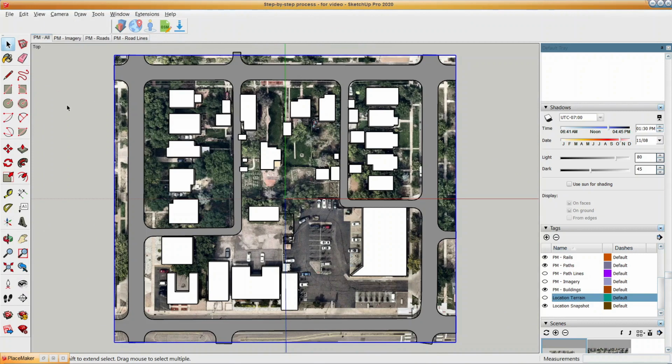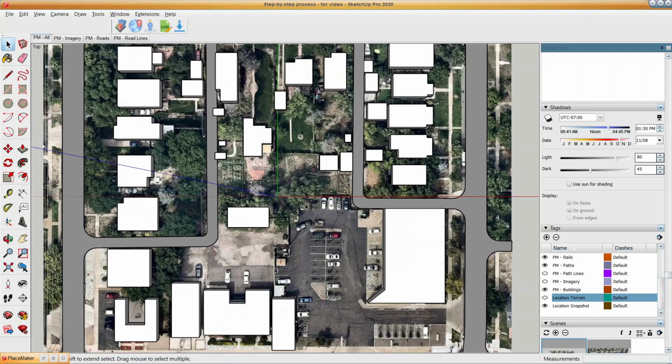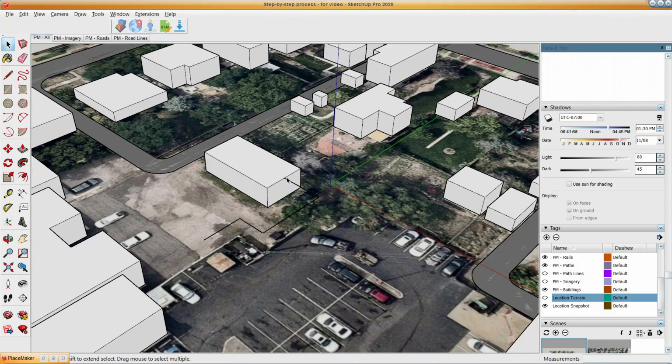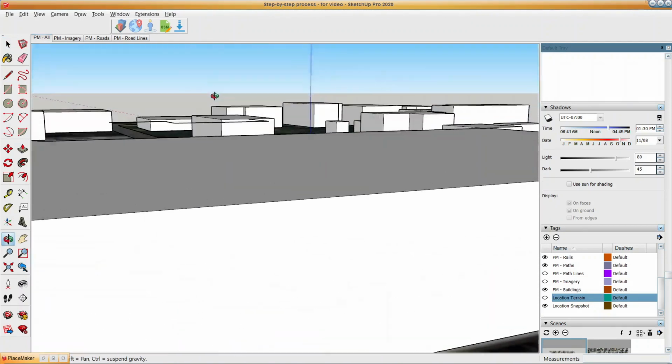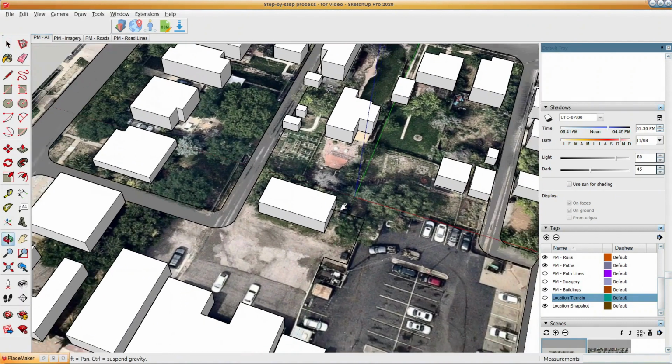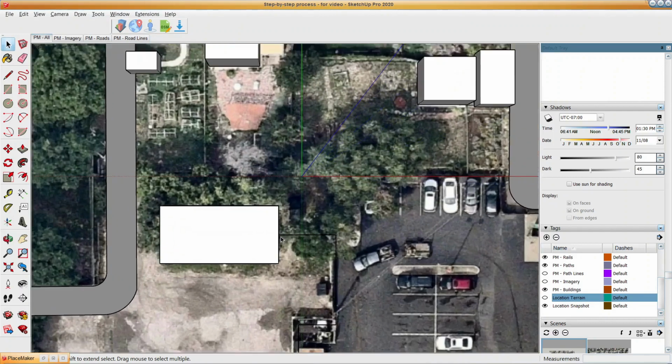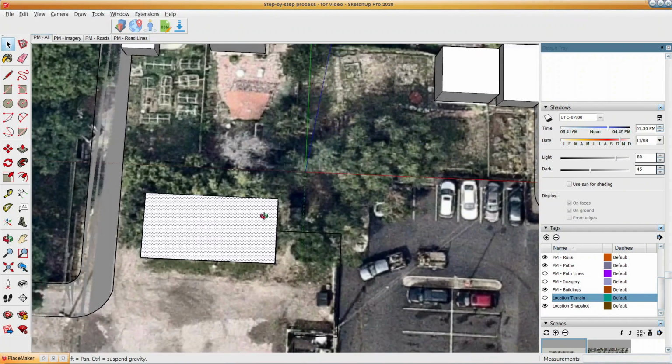And actually, before the paths, I'd recommend tracing the larger components, such as green and asphalt faces. But we do face a problem here. If we try to trace along the edges of the building, when I alter the view, you'll notice that the lines are floating in the air at different directions. That happened because as we go back to the top view, the lines we connected to the buildings were the rooftops, not the ground surface.